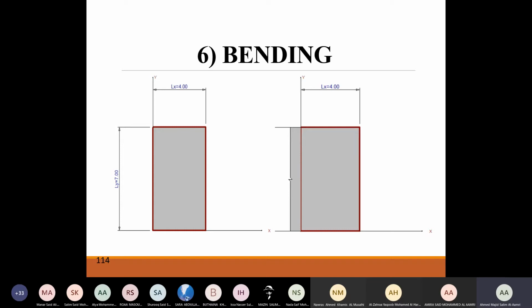Now for me, I need to evaluate and analyze these two cases, and then I'll say which one to take, or which bending moments to take. So what I'm going to do, you can see that the bending moment in both scenarios are different. Let's call this one x positive 1, and then we have x positive 2. Since we have two values, I'll be taking the maximum of the 2. Why am I taking the maximum of the 2? If I take the maximum, it will be safe for both scenarios. If I take the lesser, it will be safe for one, but it will fail for the other one.